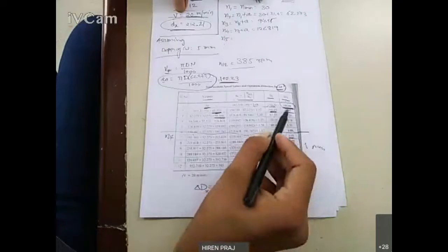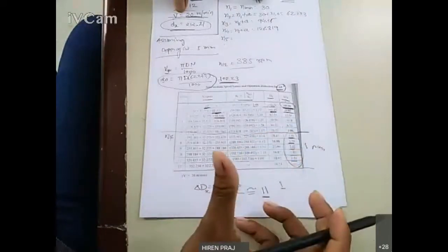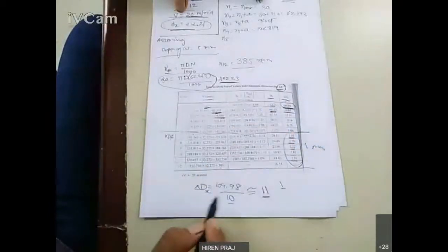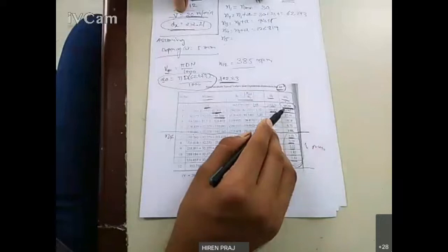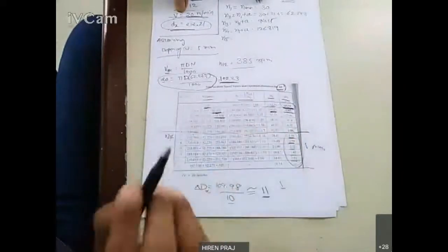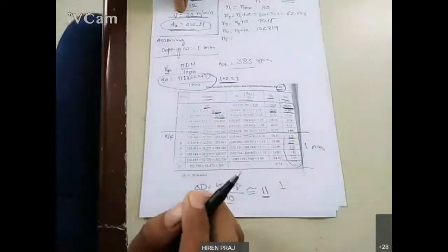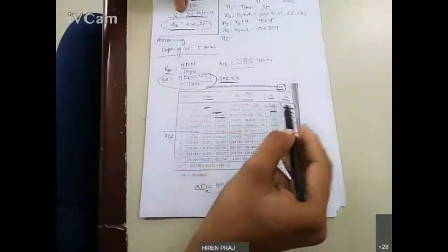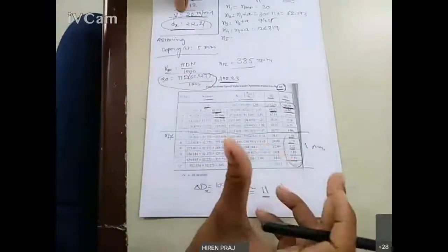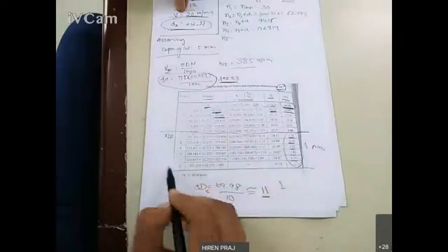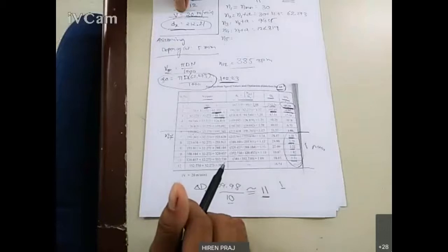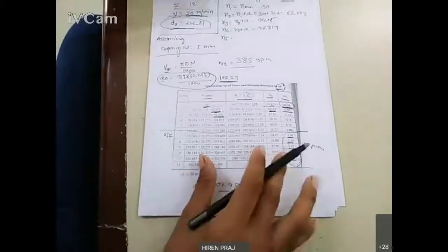And the lower RPM ranges are very broad. So here we need to provide more speeds so that this loss of economical speed can be reduced in the lower RPM range. So the conclusion is, if you are following arithmetic progression series, the lower RPM ranges are very broad, and the higher RPM ranges are very close and redundant. Clear? So this is the issue with the arithmetic progression series.